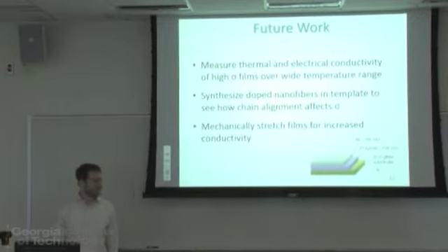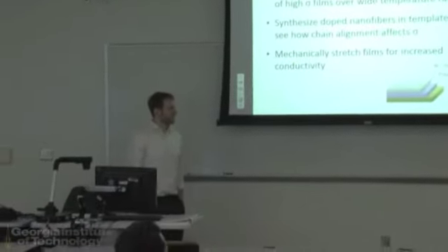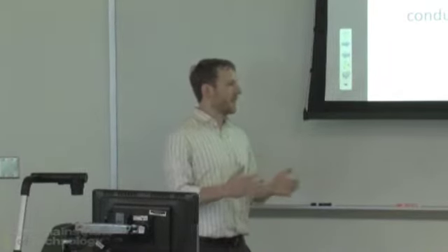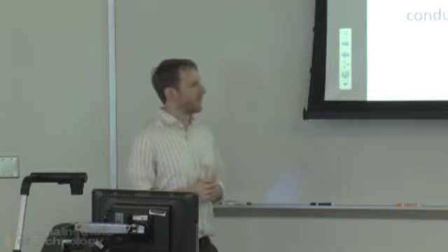Let me start. I was wondering on what time scale do you measure the changes of the temperature? You have that control. So we typically measure about 100 picoseconds out to about 7,000 picoseconds or 7 nanoseconds. So about 0 to 7 nanoseconds. So it's a relatively short time scale, but it's still an area where diffusive transport still dominates. So really not looking at ballistic transport.